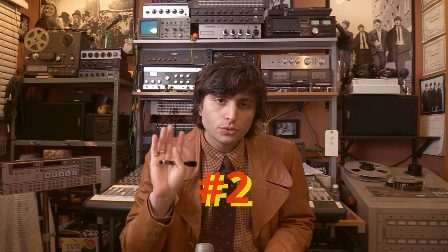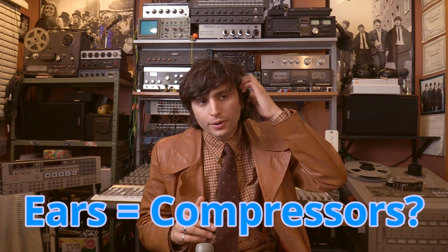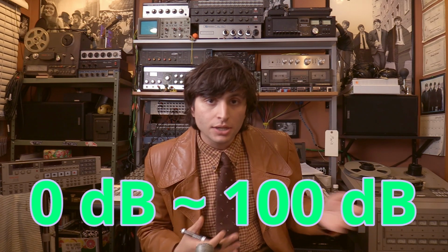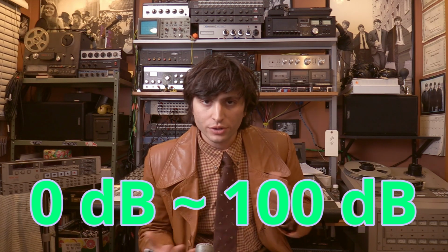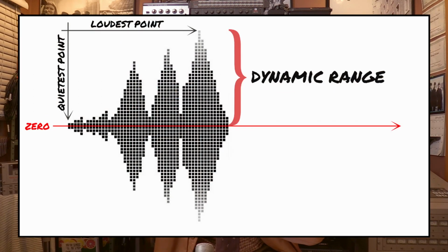The second thing I want to talk about is that our ears and brains somewhat act as compressors. On a daily basis, we hear sounds anywhere from the range of 0 dB to about 100 dB, give or take. And we're able to adjust to those different sound levels with ease. Microphones and their associated equipment are not going to be able to do that. You are going to need to change the gain settings on your mixing board to compensate for different levels of dynamic range when you're recording sound, right? So you need to think about this when you're using a microphone on any source.